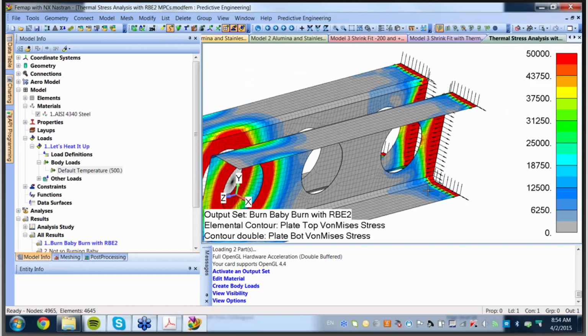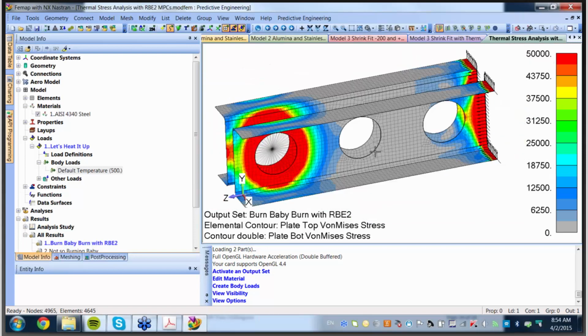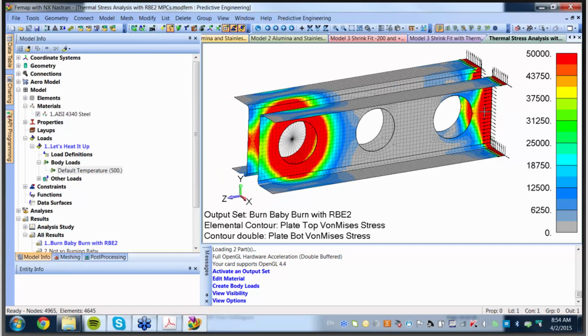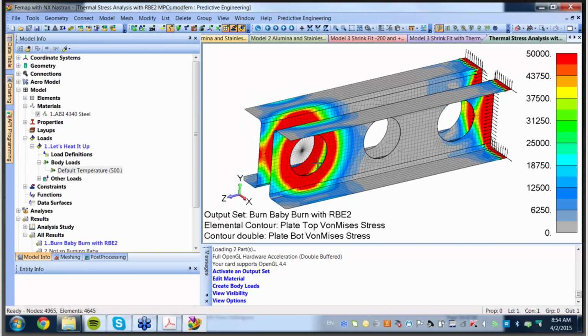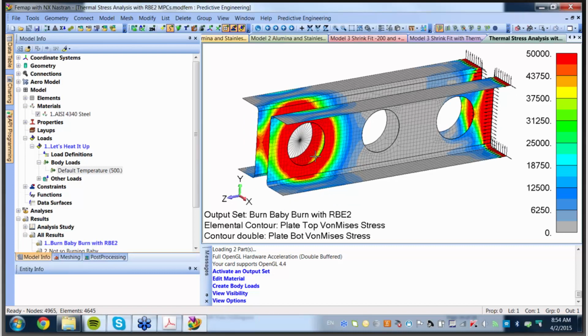It's a little easier to figure out how you're doing, so that's a pinned. So what's happened seems logical, I think, if you go, well, that's constrained, so it heats up, so the stresses just blow up. But here's your RBE element. And for many years, if people have been around using Nastran, you just groan and you switch over, use an RBE3, or you would switch it out and use beam elements, like a real beam element. You would map it out to capture, not to have this constraint.